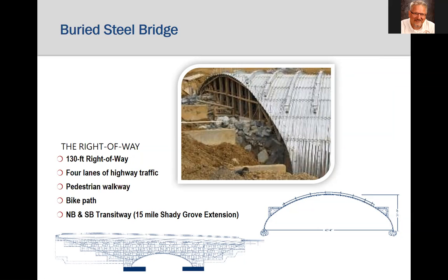With 4 foot of cover on one side and 12 foot on the other, the structural plate arch culvert is designed to safely withstand highway truck loading and design railway loads for the metro tracks. The arches are shipped to the site in stacks of curved plates, bolted together to produce the arch, and lifted into place with light construction equipment, as we saw in Lecture 5.